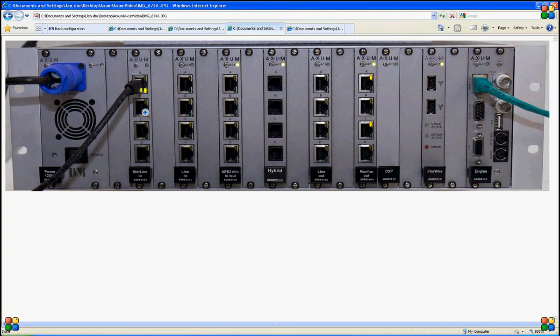We see a microphone card. Every RJ45 connector means one balanced mic input. So we see here 4 mic inputs A, B, C and D. But every input also has 2 GPOs and 2 GPIs. The line input RJ45s are designed to have 2 balanced inputs per connector and 2 GPIOs.